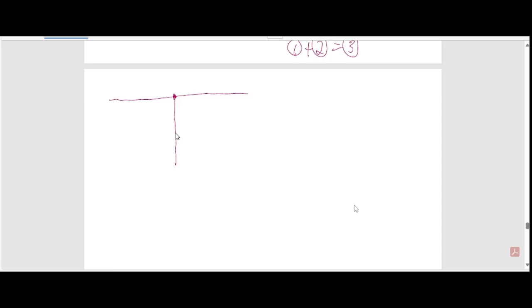Anyway, we started already and I recorded it, so watch the first piece if you need to, but I'll just continue. We just did KVL and KCL, so I'll go through it one more time. All KCL is, you see there's a junction. You'll see this all over the questions. The sum of the currents entering is always the sum of the currents leaving. So if this is A, this is B, and this is C, this here is the junction. It's good to draw a dot on it to make it a little bigger.